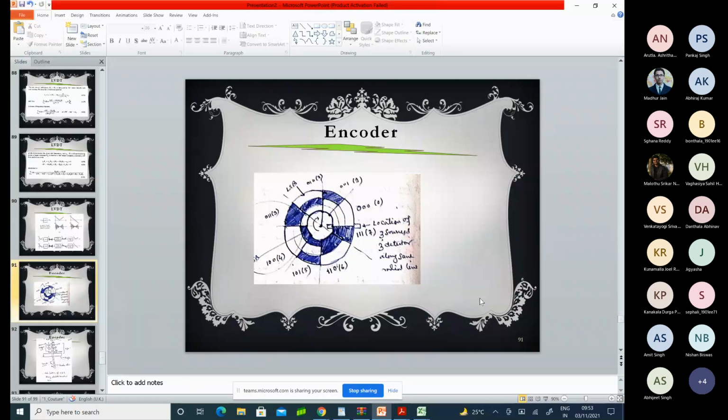And what about the incremental encoder? Incremental encoder will give the output, which is the incremental increase of position or velocity. So if we want to know the absolute value from the incremental encoder, you need to know the first point properly, and map that point with the absolute position. Then the incremental output you get, you have to keep on adding on top of that point. Then you will get the absolute. So from incremental encoder, you can get the absolute values. You need to have a reference and keep on adding at each sampling time. Okay, that is the point.